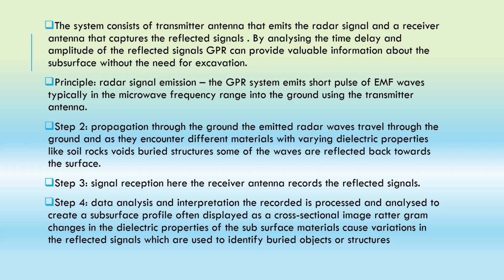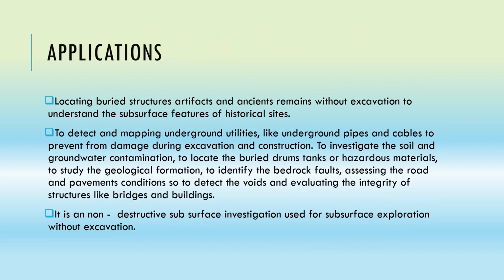In the case of archaeologists, if there is any kind of system that has been buried underground for like 50 years, or there is a building inside the ground, using these signals we can identify the buried objects or even the structure using GPR. As we saw in the steps of GPR, the first application is finding subsurface historical sites, identifying buried structures or ancient remains which are not known to the human eye. So we can identify them using GPR.